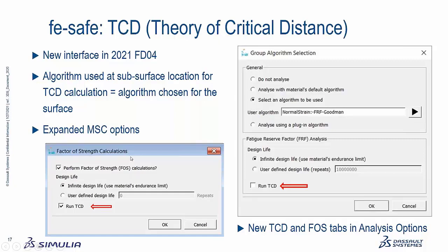calculation. And sometimes you would even get the subsurface calculation showing you worse life than you would get from your crack initiation life. So they were going to the extent of doing their own workarounds in the post-processor where they would just sample stresses at the subsurface levels based on the material characteristic length or the critical distance length.